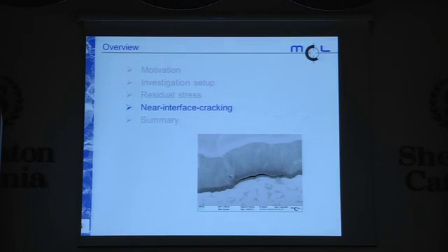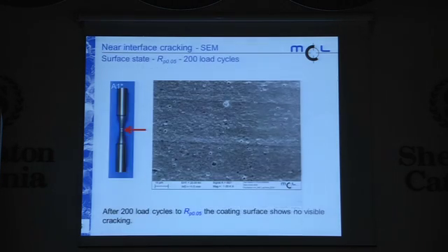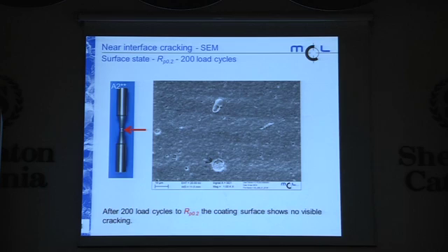We looked at the specimens closely at the notch root. We looked at the surface and saw, well, there are no cracks. In none of the specimens were there any cracks really visible. This is what just ripped off, arc-related droplets, those holes, but there were no cracks visible.